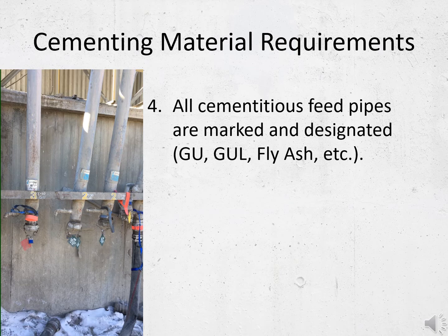All pipe stems, where pneumatic trucks hook up to transfer products into silos, should be clearly marked with the cementitious material product type, and in some cases, the product source when multiple sources of the same material type are used in production. Any product type or source switch information should be entered immediately into the batching system to ensure any program proportioning adjustments are included in subsequent loads of concrete produced.